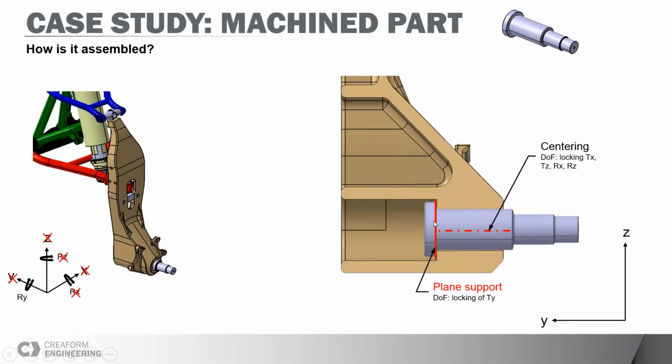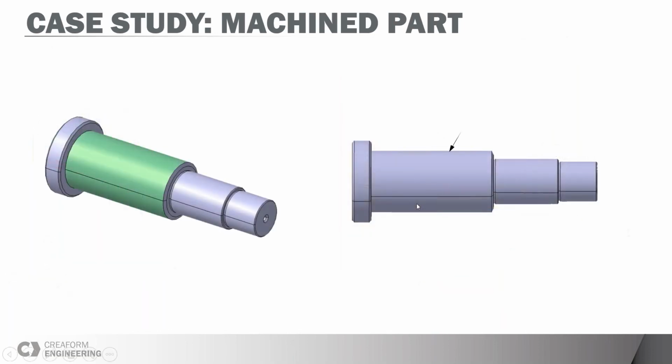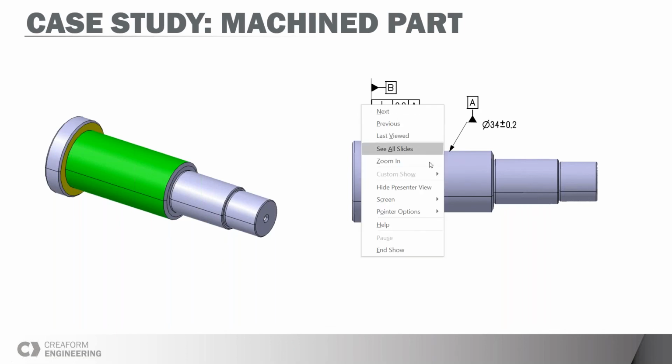The defect of perpendicularity that we will have between the shoulder and the diameter will actually create kind of a gap between the spindle and the knuckle. So the way we would define this one is by choosing the maximum amount of gap we are able to allow between the shoulder of the bolt and the knuckle. So this is for this one.